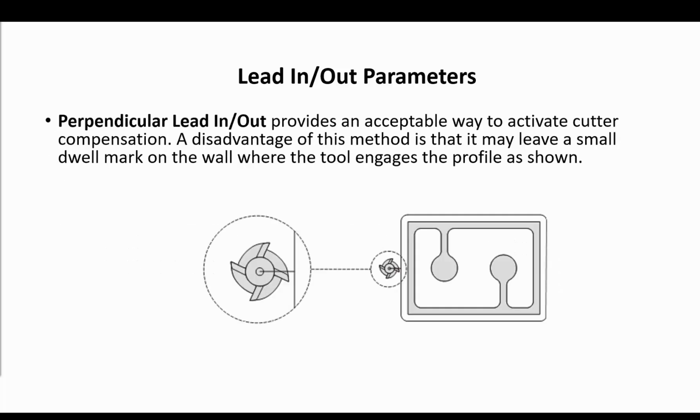Perpendicular LeadInOut provides an acceptable way to activate cutter compensation. But a main disadvantage of this method is that it may leave a small dwell mark on the wall where the tool engages the profile.